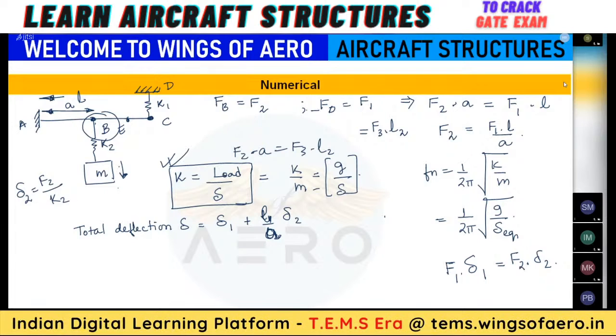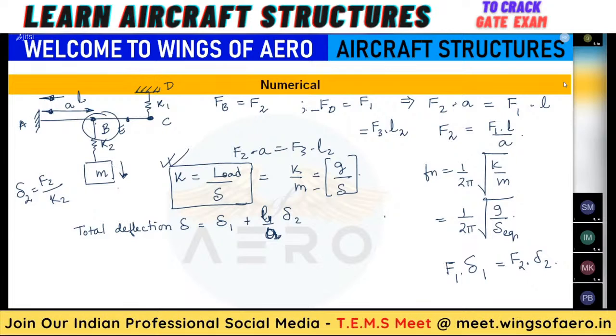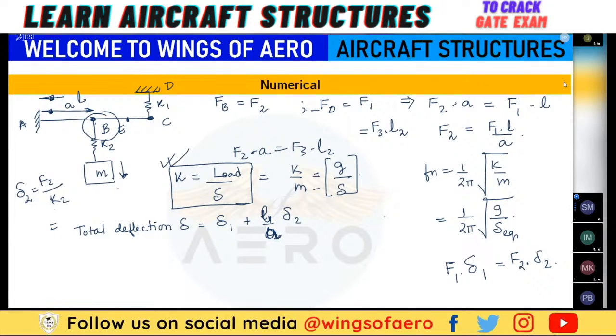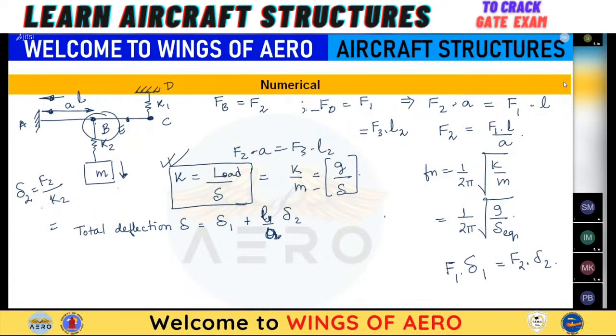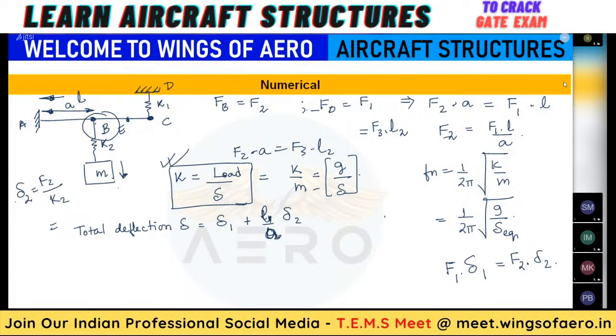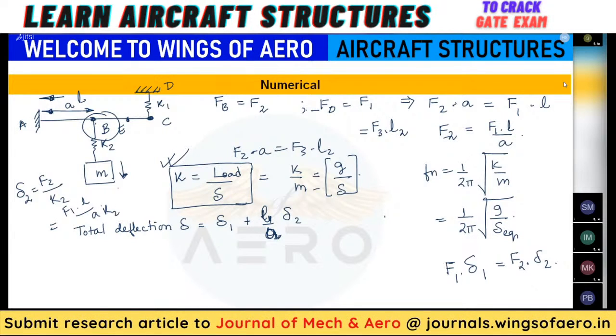Could you follow? Ma'am, again, this equation is also from derivation. F1 delta 1 equals F2 delta 2. Yes. So from there you can write delta 2 equals F2 by K2. Now we know from here F2 means what? F1 into L by A. So can I write F1 into L by A into K2?